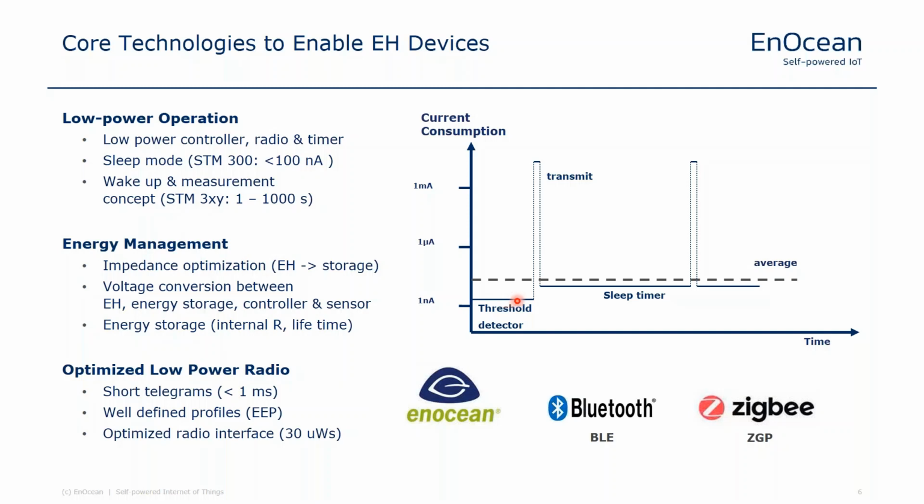self-powered sensors. Most of the time, it is in sleep mode and requires very, very little energy and current. And then there is some operating and transmit phase. And then you see, for example, in this case, we have 20 to 30 milliamps, which is very high for a self-powered sensor, but only for a short time. And then most of the time you're going into sleep. So de facto it's more than 99%. And that's the magic behind it.